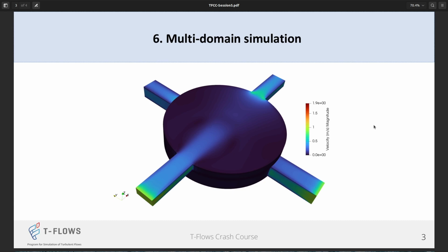You can think of it as a heat exchanger, but the difference is, first of all, we don't have explicit mixing of the flows. They're just laying on top of each other, and the mixing is happening through temperature. So the temperature from the top domain is affecting the membrane, which is something that is insinuated in between. And temperature from the lower domain is also affecting, from the top surface, the membrane from the bottom. So everything will become very clear when we visualize them in ParaView, but I just wanted to give you some outline.